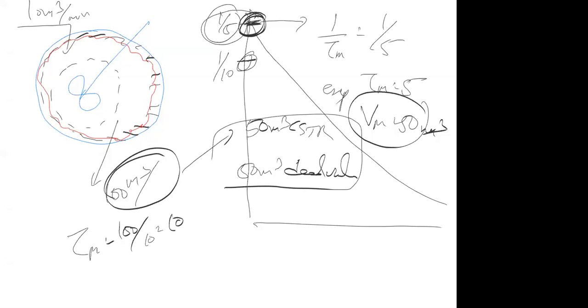If this is the case, then you should put more stirrers here so that you decrease the dead volume. If you put more stirrers, then the electricity cost increases. So imagine that dead volumes will always be there in most of the reactors.